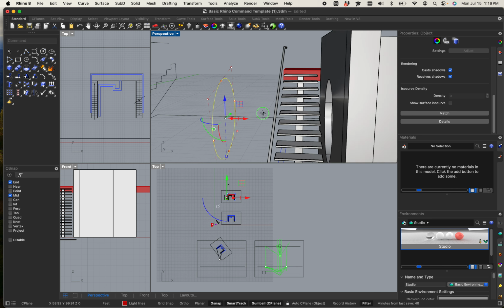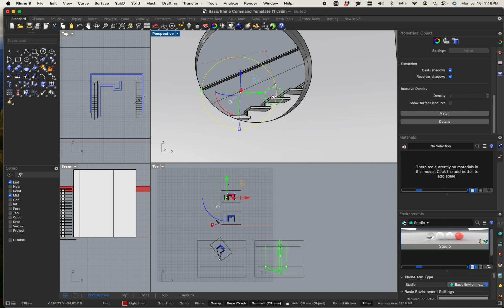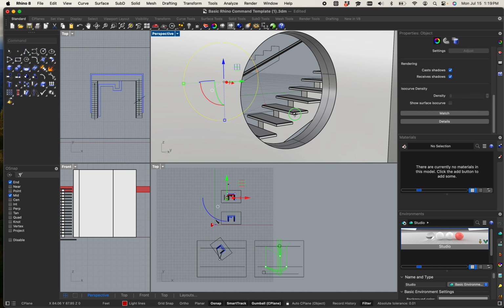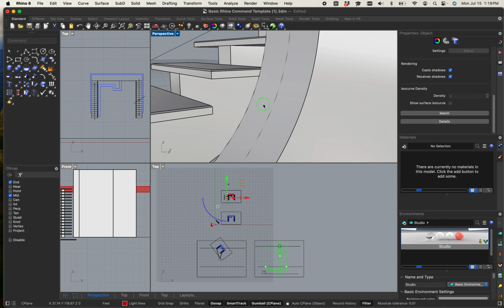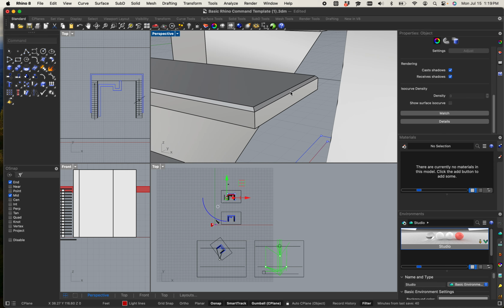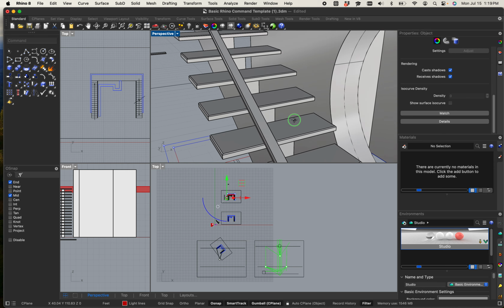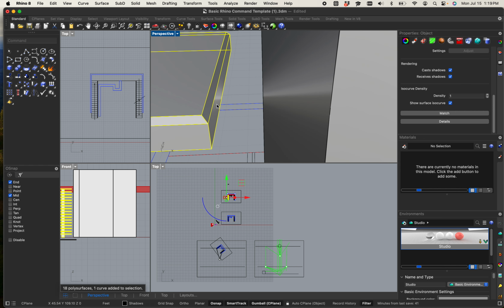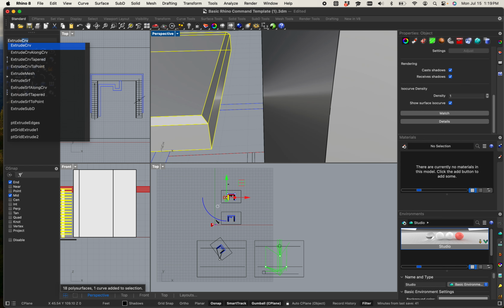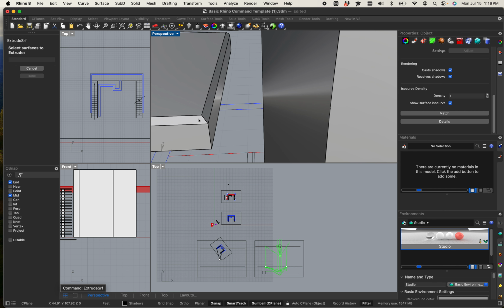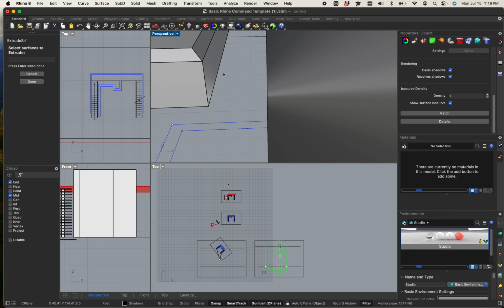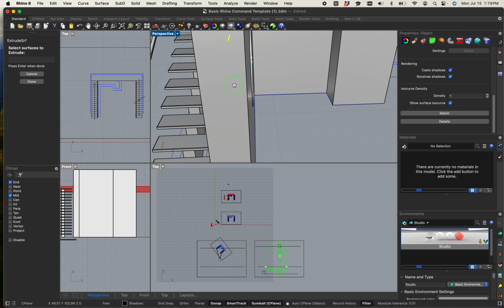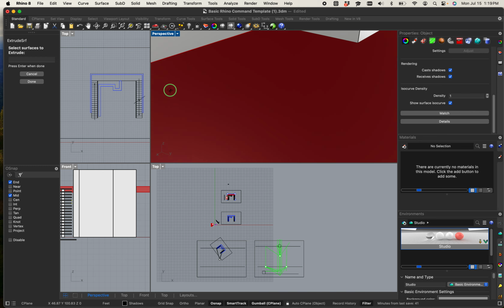But as you can see, modeling this guy and making it a little bit extra is not a hard task, right? Arguably, we can even start to get fancy and start connecting these, and again, just further making the excitement of the architectural modeling process, right? For instance, I could take this surface, I can extrude surface, take this one right here. Oh, I don't want that one. So I can hold my control bar. I can hold shift as well.